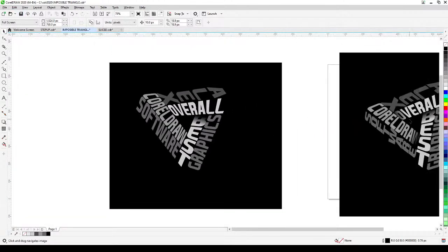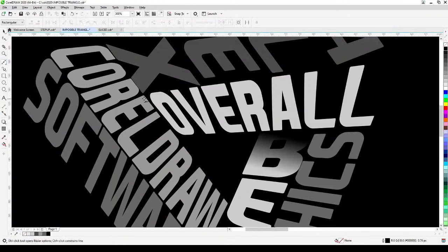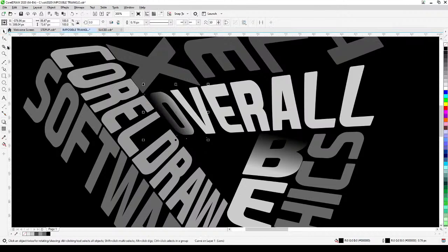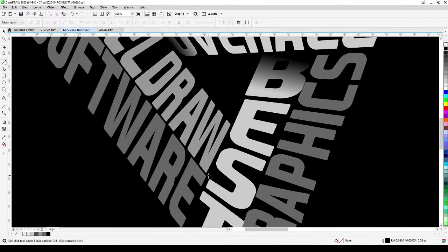Okay, and what else do we need to do? It's this one over this one and the W. So here you go to your Bezier tool. I'm just gonna create a shape. And then make it black. And then I'm going to go to transparency tool and just have to adjust a bit there so that you have like depth on the letters. So the last one, go here. Okay, and then I'm going to close that, make that black, and then I click and drag. There you go.